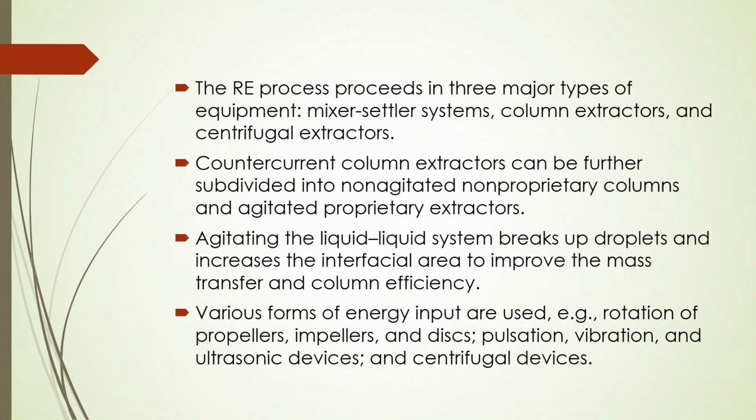Now, if you compare ejectors and motionless mixers, you will see they may have similar mass transfer performance at a given gas-liquid flow ratio and energy input. And the reaction engineering process proceeds in three major types of equipment: mixer settler systems, column extractors and centrifugal extractors.